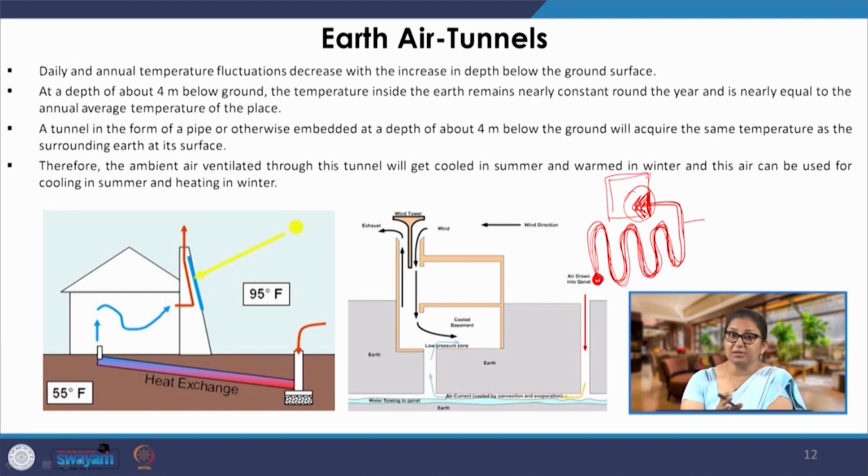A similar concept has been used in the desert climate in Middle Eastern traditional buildings. There they draw the air to the level where there is an underground stream, and they allow the air to pass over the stream and be cooled again evaporatively, and then we take the cooler air into the lowest story of the building, and one story of the building will also be submerged, underground.